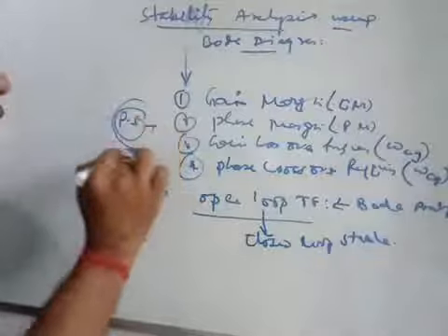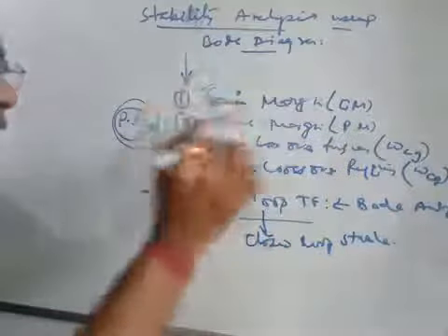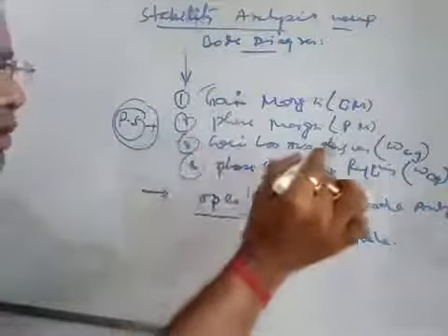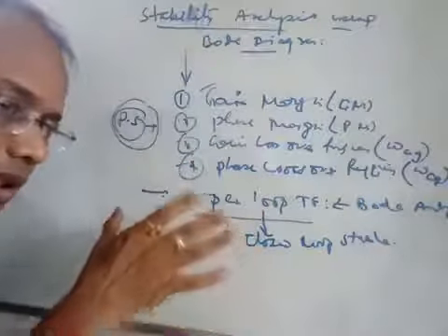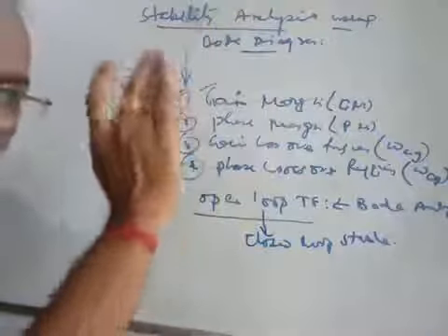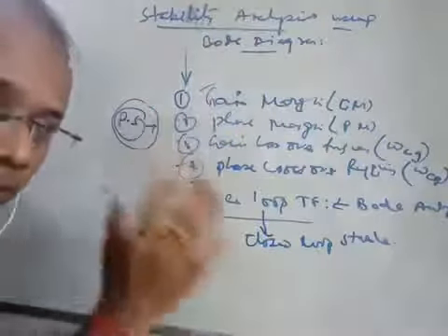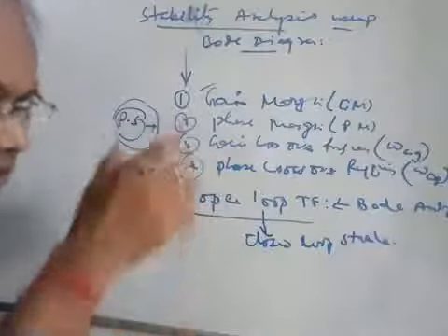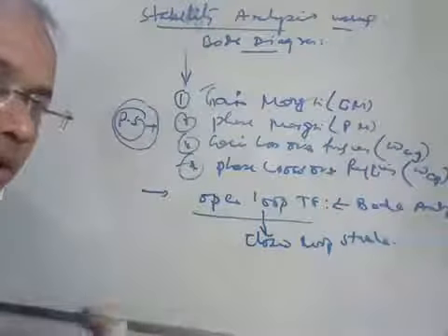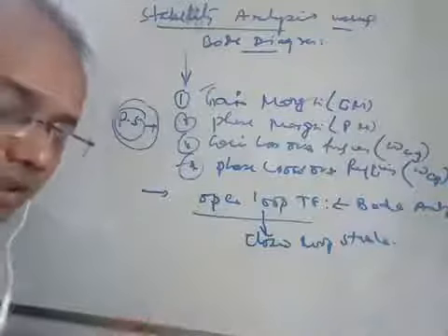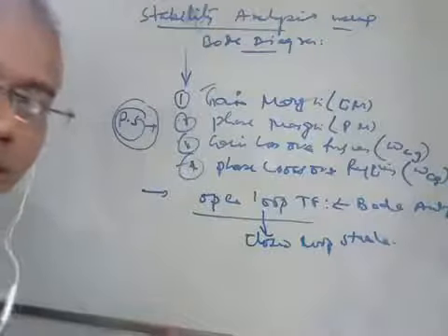So these are the performance specifications of the frequency domain: gain margin GM, phase margin PM, gain crossover frequency omega cg, and phase crossover frequency omega cp. Now we will draw an arbitrary graph; for any system, maybe the graph will be like that. The semilog graph paper gives you a view of how the Bode magnitude and Bode phase plots are drawn. From these plots, we will study how to find the gain margin and phase margin, and what the values of phase margin, gain margin, gain crossover frequency and phase crossover frequency should be such that the system can be stable.